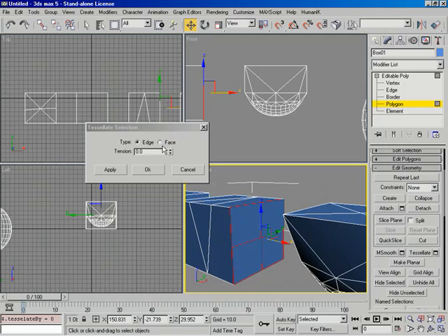Right. Okay. If we switch over to face, what face will do is actually slice, if you will, or cut from the edges or the corners of the selected polygon. Okay. So rather from the middle of its holding together edges or from the corners of the edges. Either or. When working with edge itself, we have a tension setting down here, which basically allows us to push in or pull out, as you can see here. So as I up that, it's now pushing out, or I can even go negative with it and start pulling it in. Very handy.